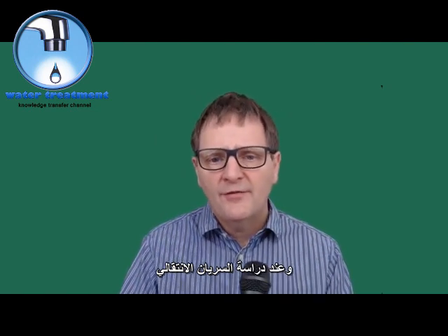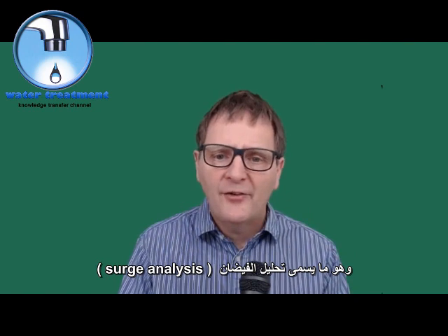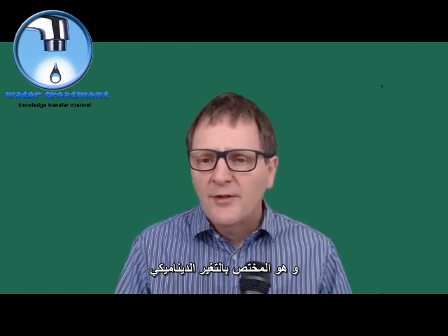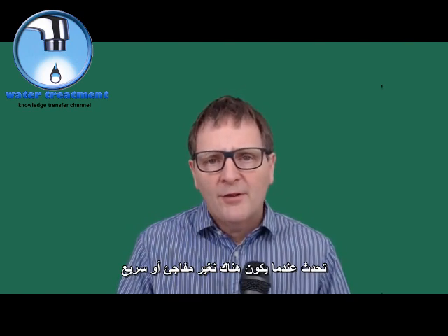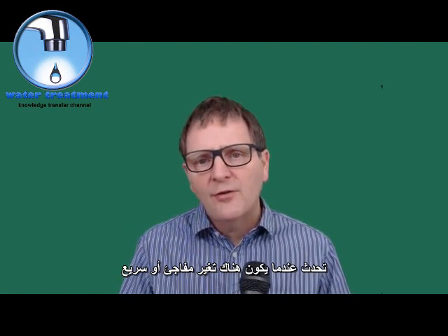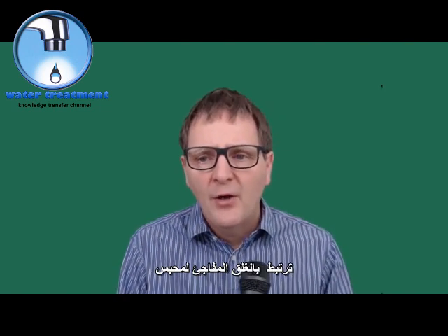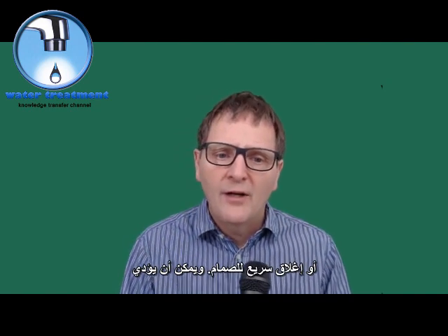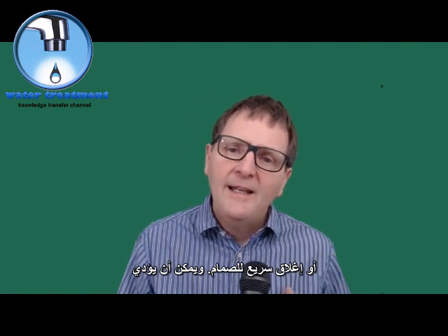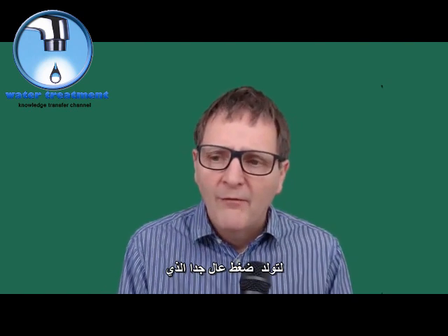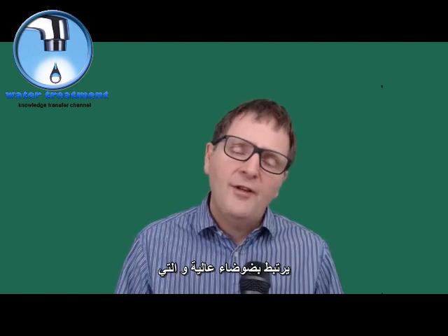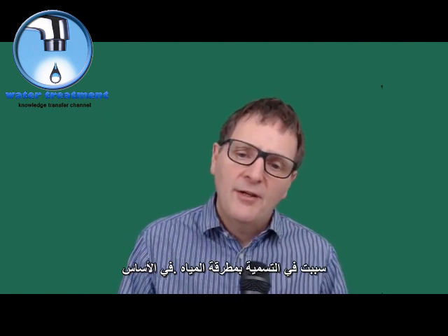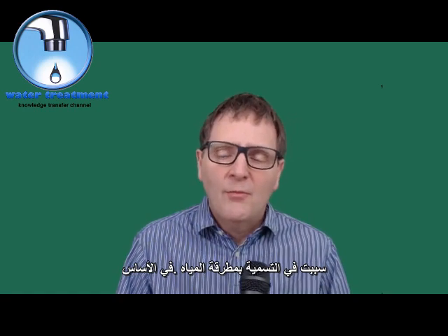Transient flow, and the study of transient flow, which is called surge analysis, is concerned with dynamically changing flow velocities in pipe. Water hammer occurs when there is a sudden or rapid change in the flow velocity. It's usually associated with a valve slamming closed or rapid closing of a valve. It can lead to very high pressure transients, which can cause the pipe to fail. Often it is associated with a banging noise, which leads to the term water hammer.